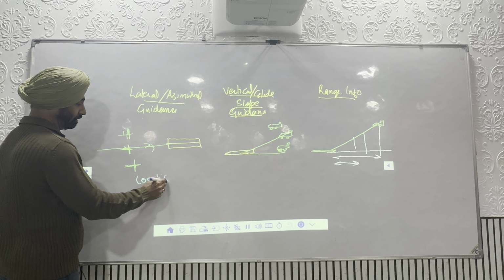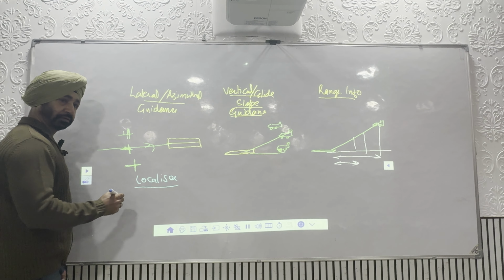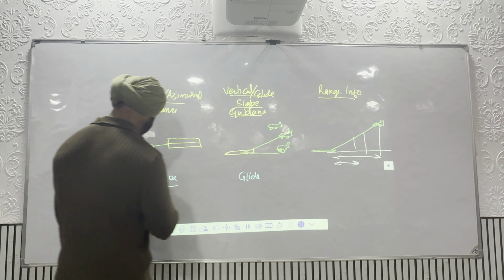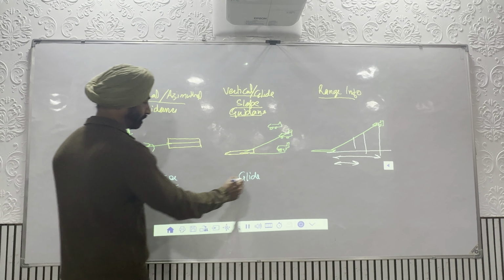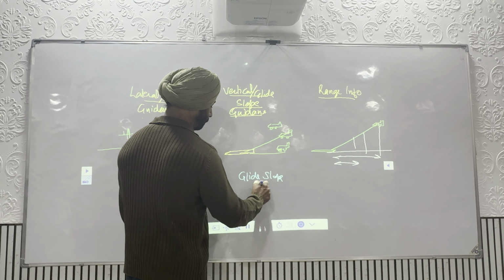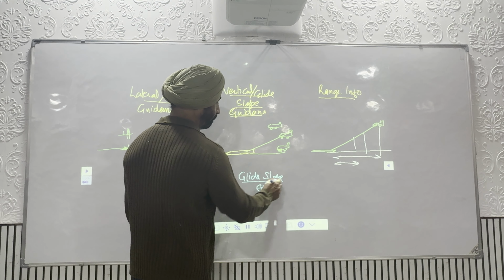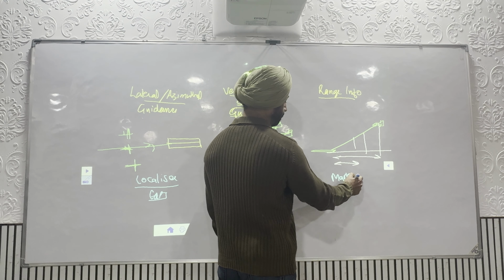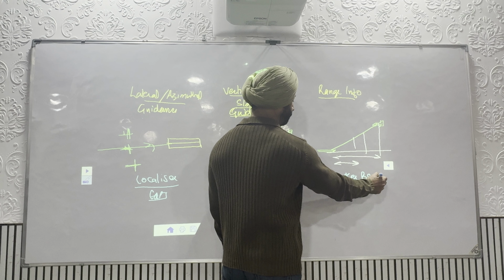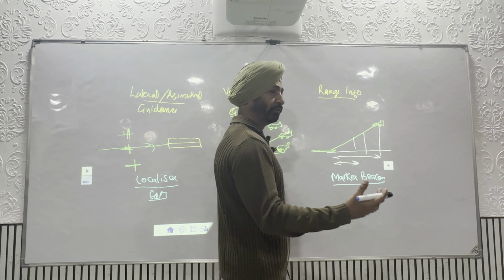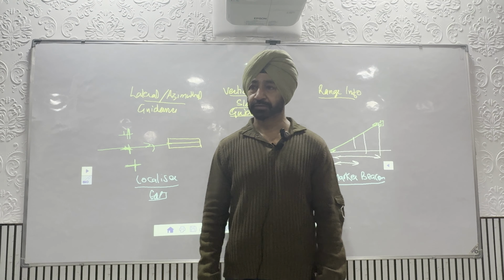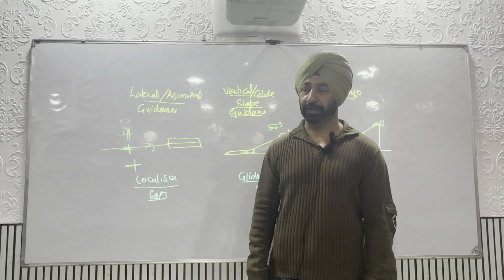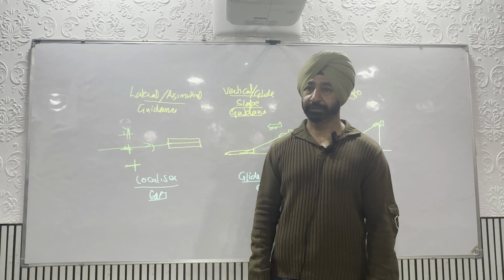So this lateral information is provided by equipment called Localizer. We have a Localizer equipment, we have glide slope equipment, and how far you are from touchdown is given by marker beacon. Beacon is anything which is giving the direction or position. You have a light beacon also. So there are 3 components or elements of ILS: Localizer, glide slope and marker beacon.